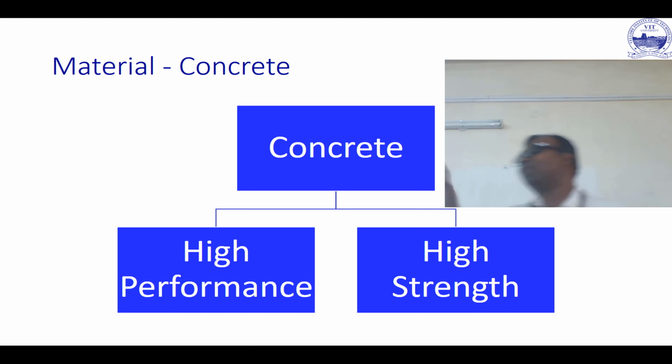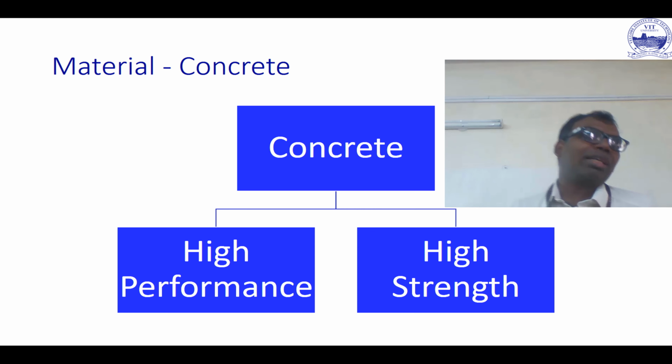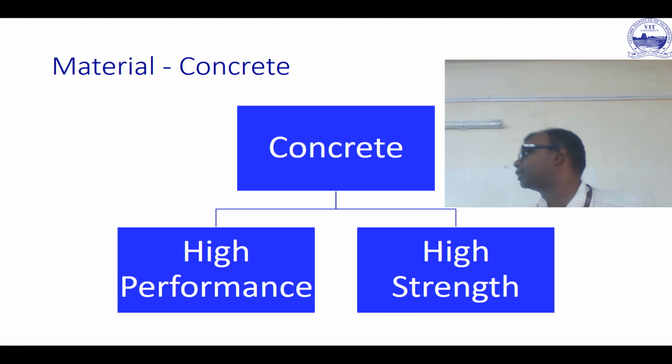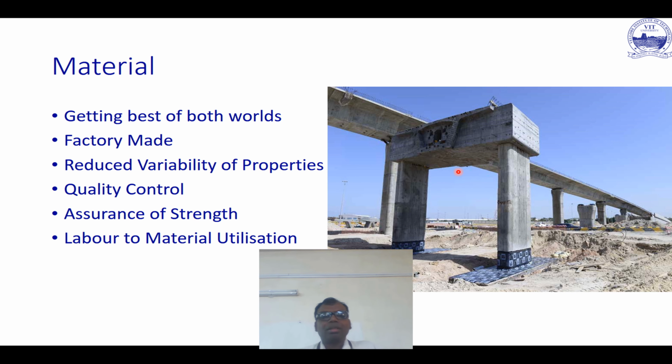Okay, so now I'm not going to go into the mechanisms of pre-stressed concrete, but when you're having a pre-stressed concrete element as a precast unit, you'll find that reduction in creep has a very big benefit. Okay, again, many of the other things, like whatever you talk of high performance, you will find that it is appearing in this particular concrete which you use. Okay, and again, you get the best of both worlds of both the steel and concrete.